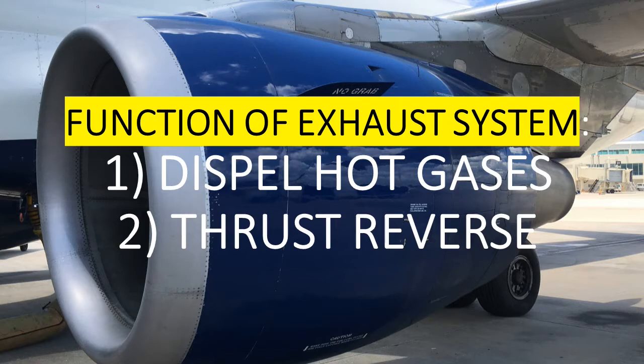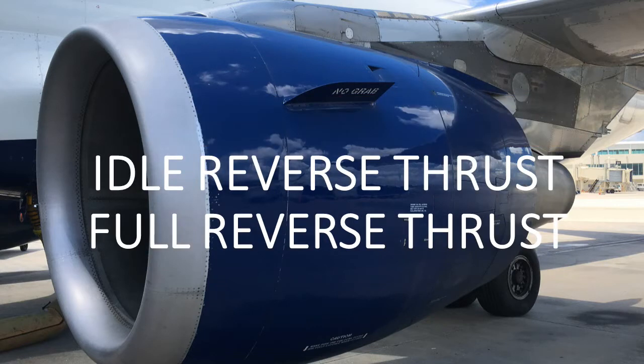There are different speeds, and from a pilot standpoint, they'll know at what point the thrust reverse has to be in place. There's what they call idle reverse thrust, and that has to be at least at idle reverse. Having full reverse thrust is rare. It would have to be under certain circumstances because there's so much noise created from it. There are levers in the cockpit where you lift them up, and that begins the execution of thrust reverse.